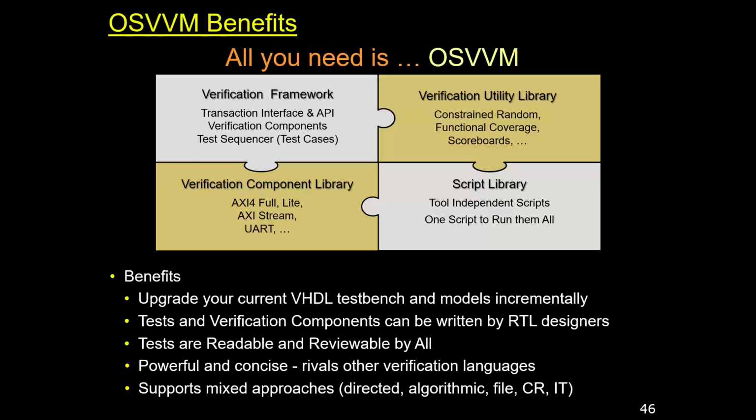On the hardware platform itself, that's not something yet I've explored. So, saying another way, our verification components currently are not synthesizable, and we're using that record interface that's using resolution functions. So until we have the VHDL 2019 interfaces and the synthesis vendors have implemented that, yeah. Okay, so at the moment it's non-synthesizable.